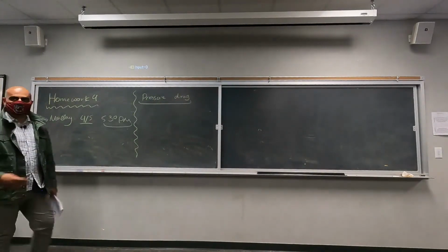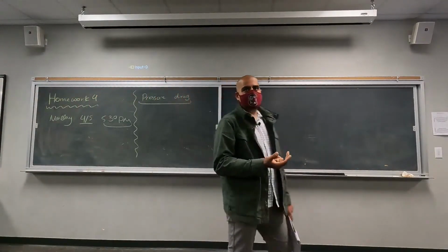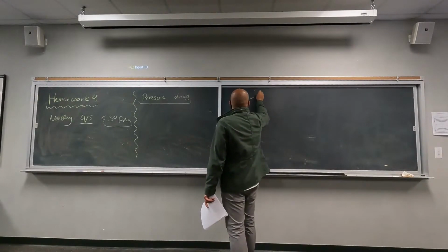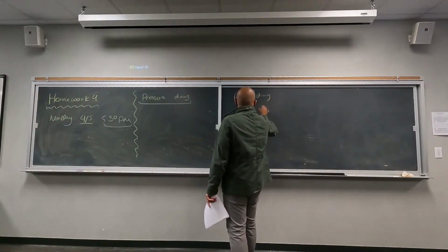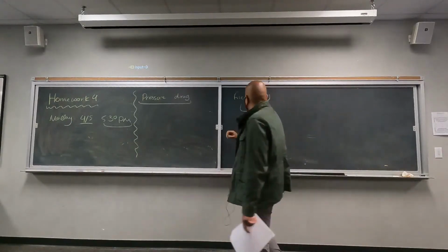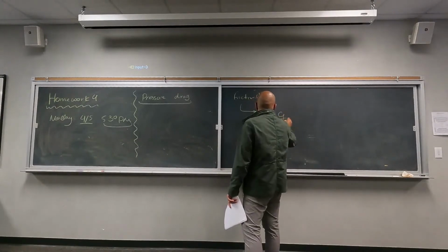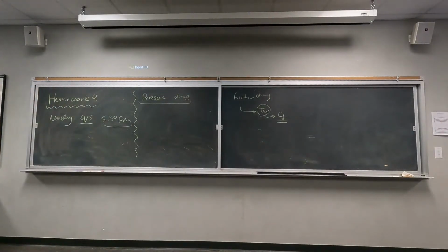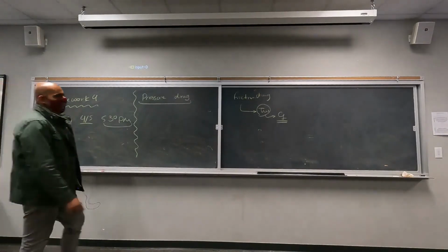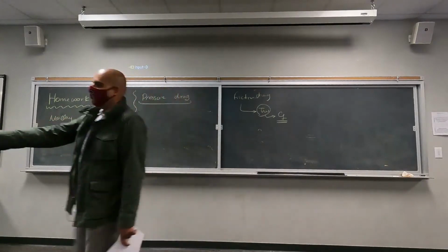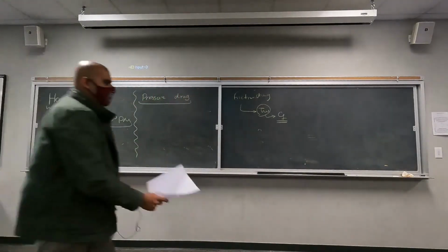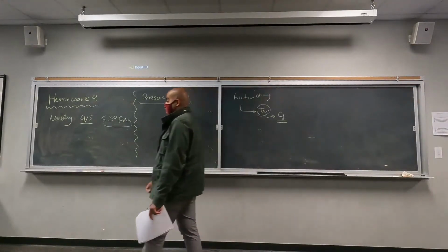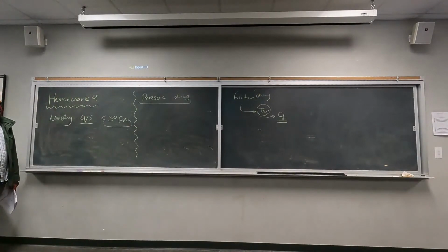We want to talk about the pressure drag. We have already talked about the friction drag. Friction drag is there because of the shear stress between the wall, or the airfoil. We actually calculate the friction coefficient; we don't really calculate the shear stress at the wall. If we calculate the friction coefficient, we can have different flow regimes, laminar to turbulent. There can also be transition from laminar to turbulent. We already know all of this, and we already know how to do the calculations. We have already solved one example from the friction drag.